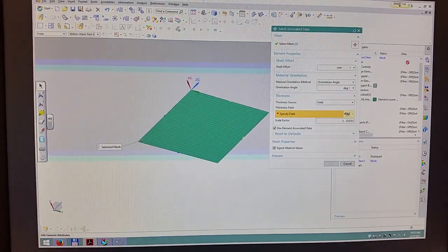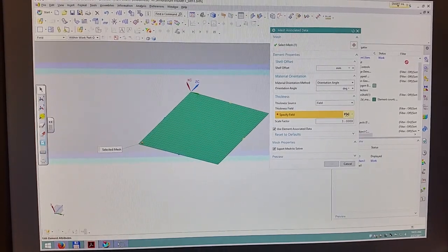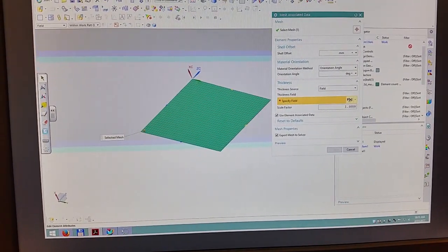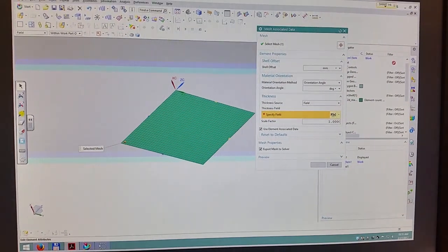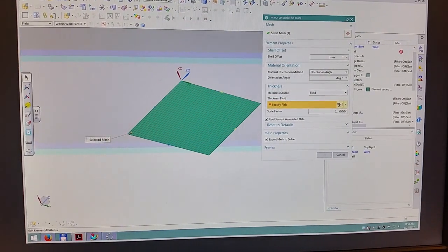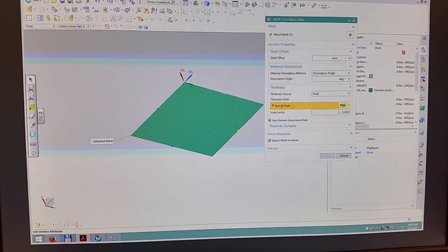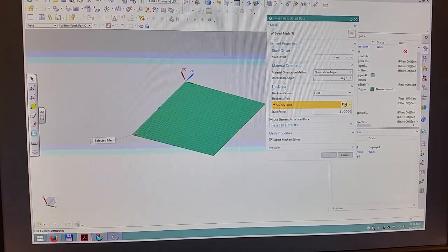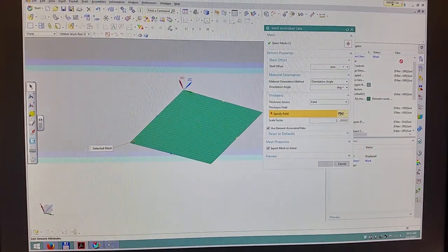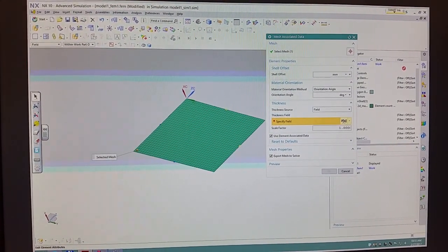By default, in between those two regions, so in between 1,000 and 3,000, most programs are like this, it's gonna vary it linearly. So I only need to define 2 points. It'll create a straight line, and then it'll use what value to use based off of that straight line. Yeah. So if you have 1 point in the middle, where instead of having 3 points on the linearly varying part, we try to do exponential, I can tell it to use exponential. Okay. By default, to create a line, I have to use 2 points.